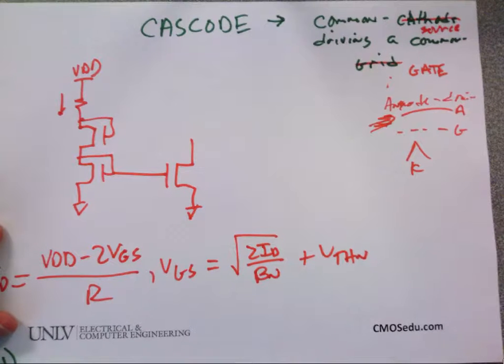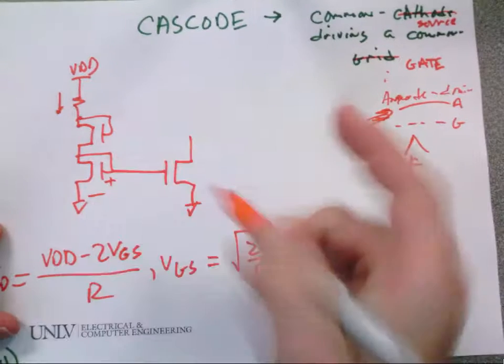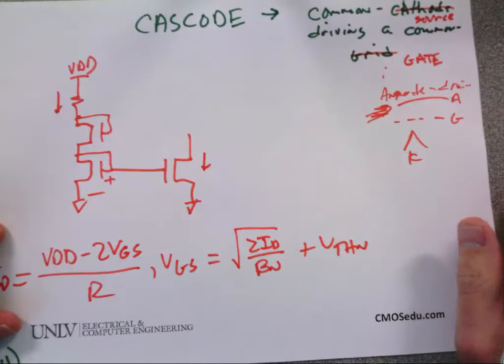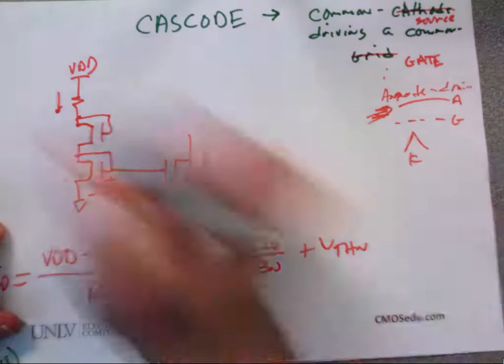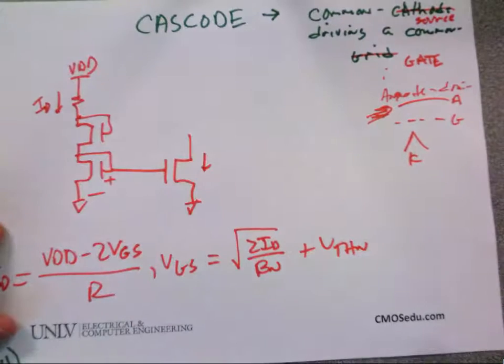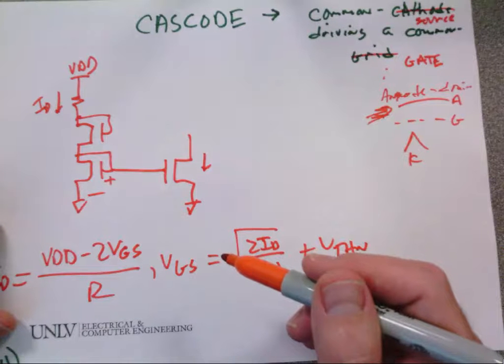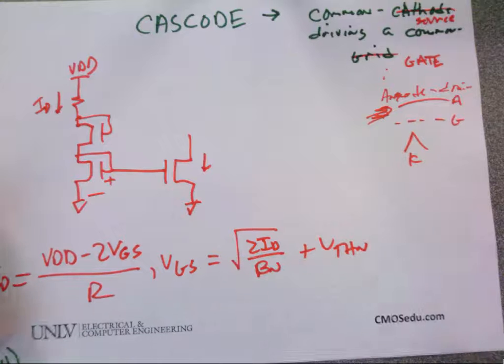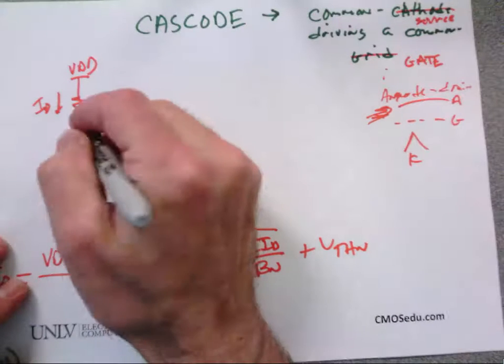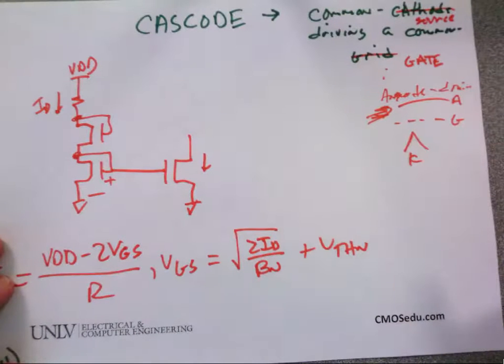Any questions? So now I calculate the VGS. These are the same size. What's the current, assuming that's in saturation? Yeah, it's the same. Does everybody follow that? Questions? So just a general question, because on the homework I kept going back and forth on it. Normally when we have the same size devices and they have the same VGS, they're going to have the same current. Yep, same size, same VGS, same current, unless they're in triode or there's a significant output resistance, which is what the resistor will normally do.